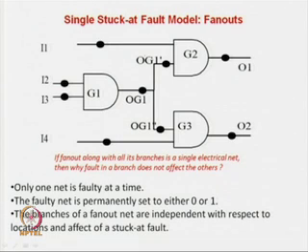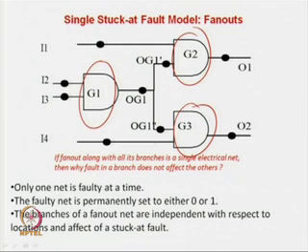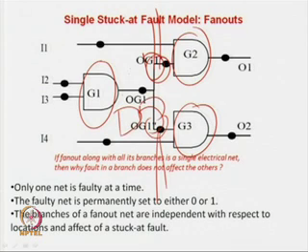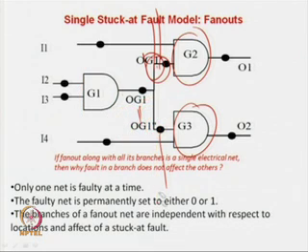So, this is a circuit. Now, in structural testing, we have to test this one individually, this one individually and this one individually. For that we have to observe this at the output, so you have to bring them to the output. Then we have to control these two to test these two things. Then you have to put a 2:1 multiplexer here, and then you have to either bring this controlling line out, or you have to have a 2-bit register here to control these things. So, that was the main difficulty in this case. Pin outs we have reduced with the registers, but that problem was still remaining.